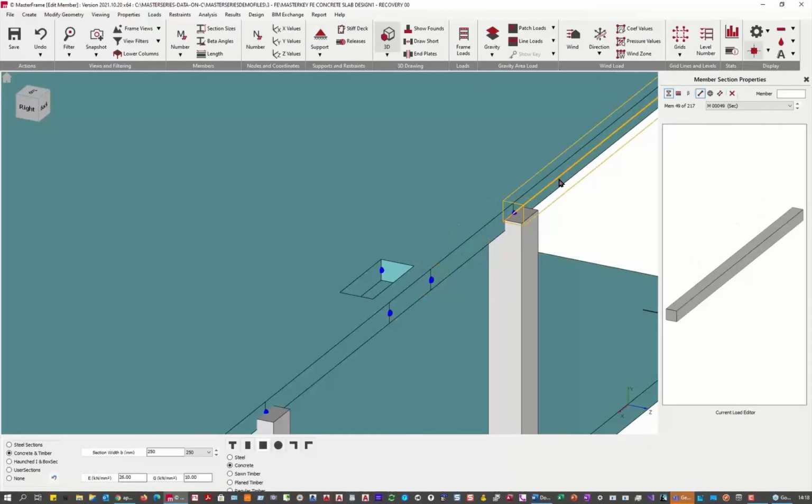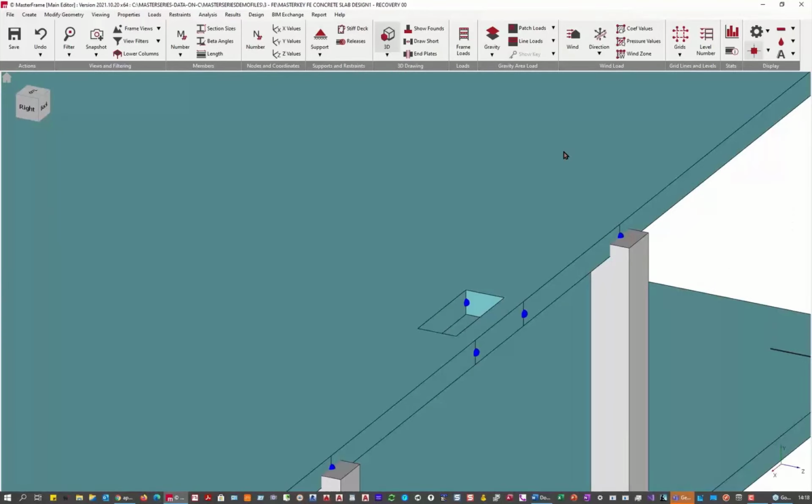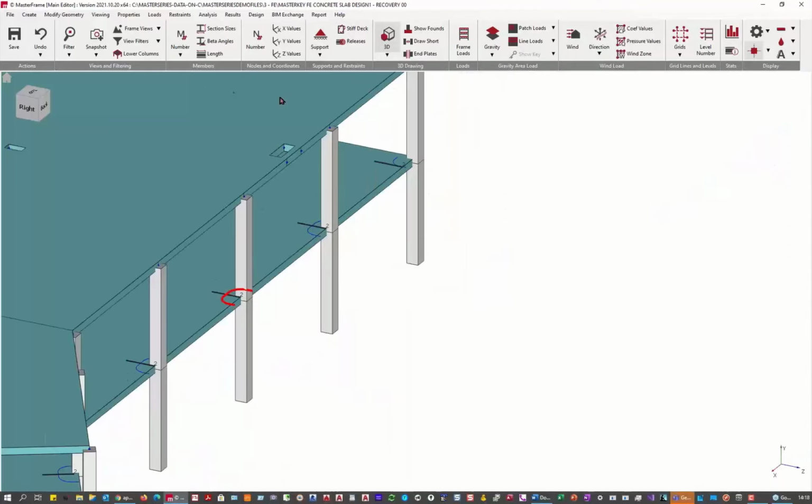Yeah, that seemed to have missed a part. That's better. So now they will all be the correct attached beams. When I go into design, analyze and design, they will now be considered to be attached to the structure and be perfectly valid. So let's mesh this out.